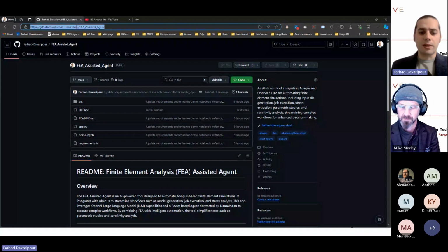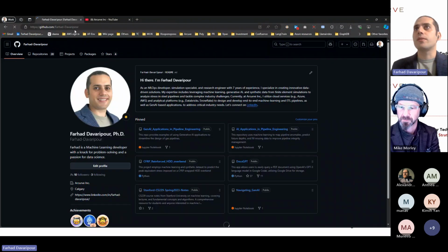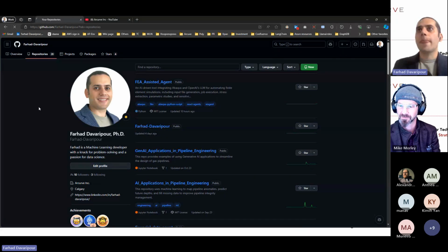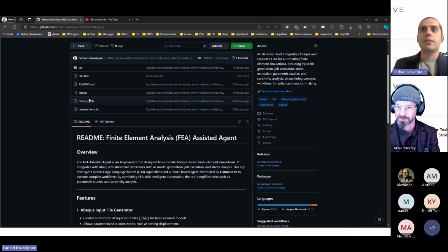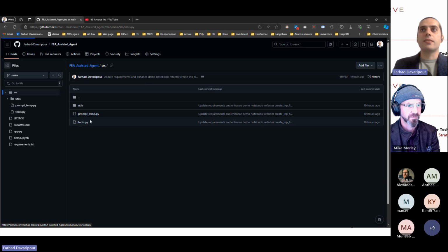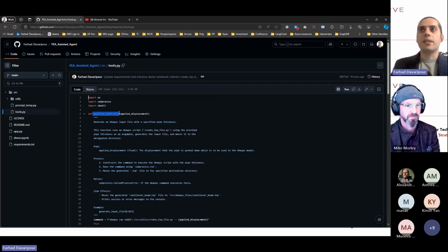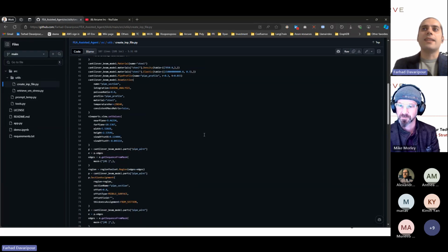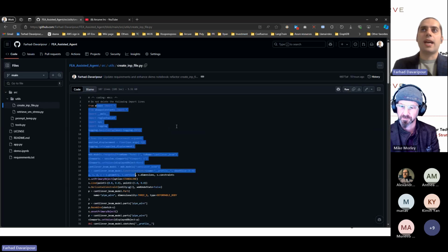I'm going to quickly show you. I've already gone to the repo at the beginning, but I'm going to do that one more time for those of you who joined a few minutes later. You simply go to my GitHub, to the first repo, and that's where you see the source code. The tools that we're going to talk about today are under src, and this is the tools. That's the first tool, generate input file, and it effectively runs this script along with other stuff. This script runs the create input file, which is under utils, and this is the kind of file that's generated by the macro when you are interacting with Abaqus.